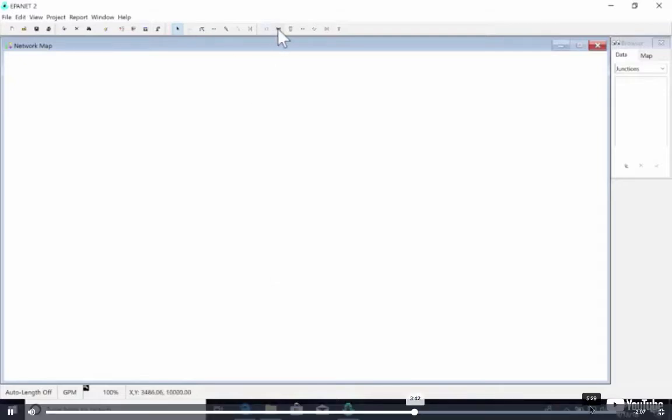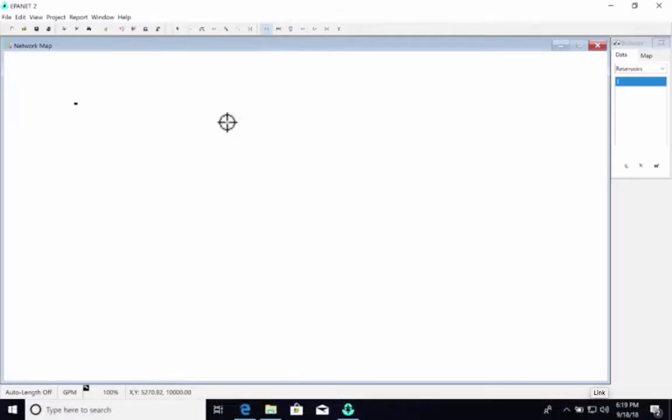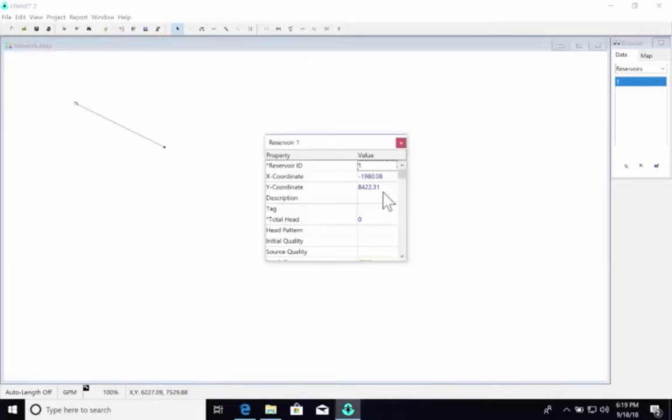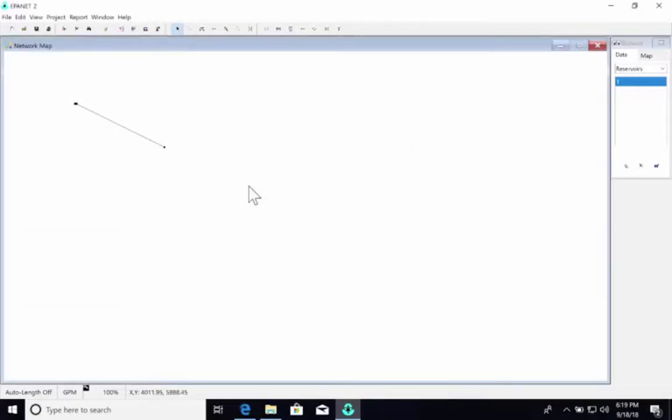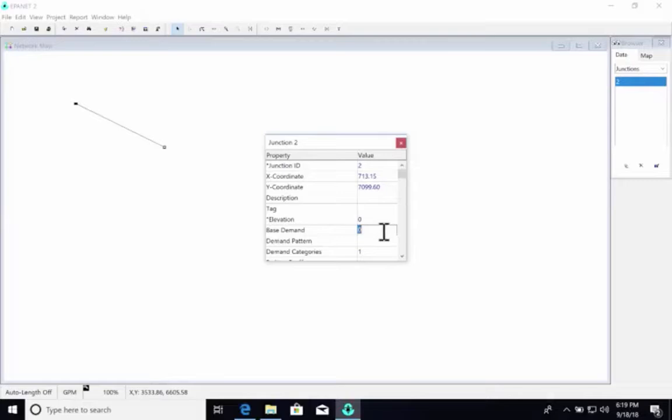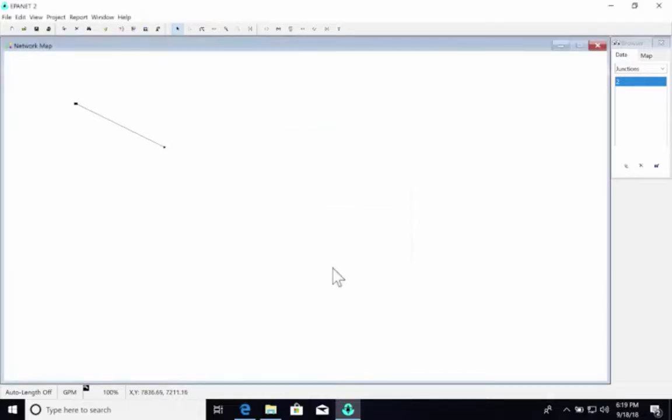If you want to check it, a real quick and easy model to build is a reservoir and a node. Connect them with a link. Set the reservoir head to something meaningful. Set the demand to something meaningful. Pretty sure the defaults will handle the rest.